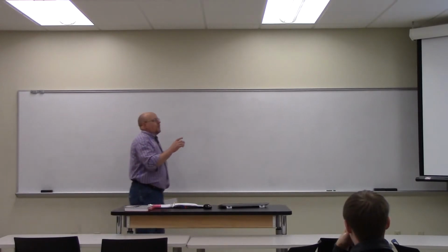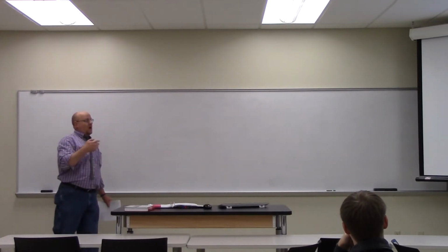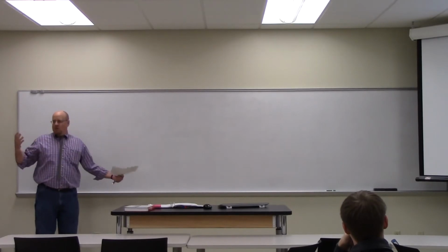Okay, and bending, so essentially we're rotating a moment. Torsion is a moment about the x-axis, as pictured here. Bending is a moment about the y or z-axis, right? Because y and z in this configuration are interchangeable in this sort of generic bending situation.